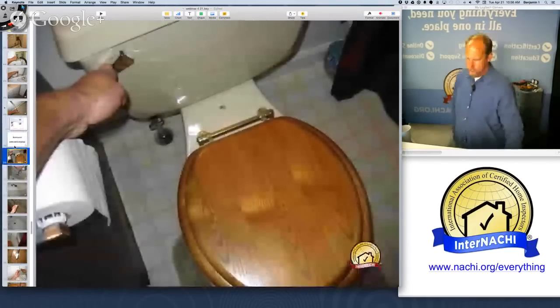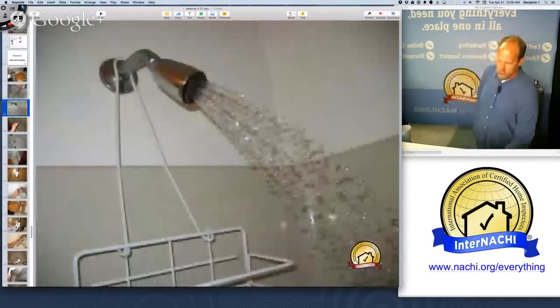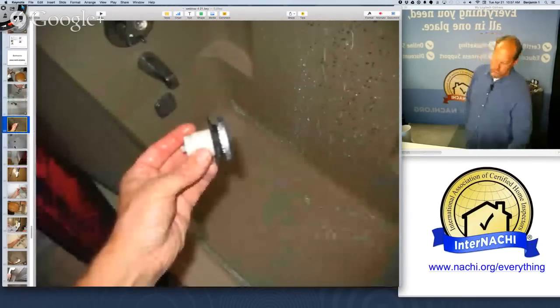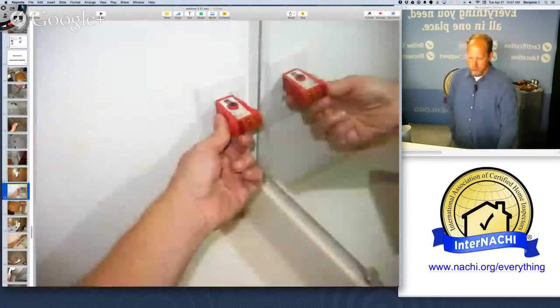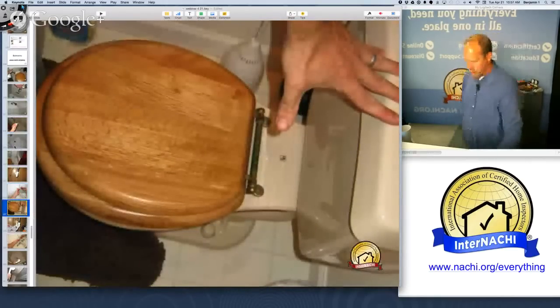And we're wrapping up the inspection by doing the bathrooms, which is very easy to do. Just run water at all the fixtures, showers, tubs. There was a chip that was repaired, and the drain plug was loose. GFCIs were tested. The master bathroom toilet wobbled on the floor.